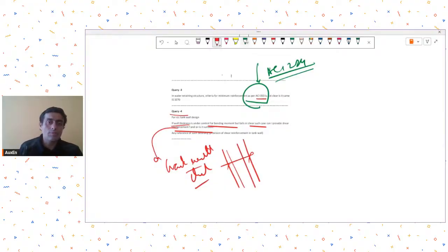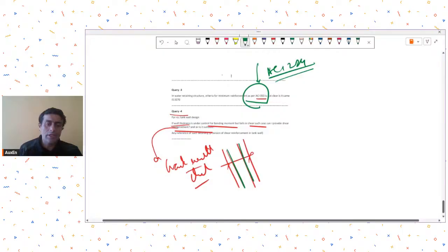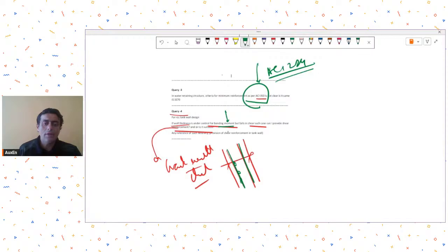Generally, that reinforcement that you will have to provide for crack width check will be more than what you require for your normal bending. And once you increase that thickness and provide sufficient reinforcement that is taking care of crack width, chances are that it will take care of the shear check also. Understood? It will take care of shear check also.